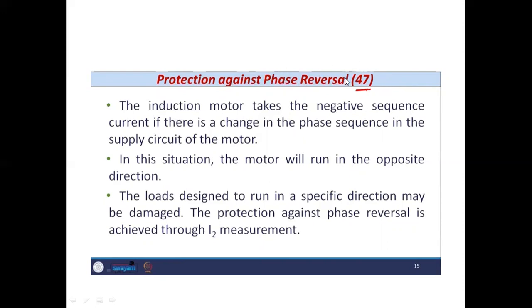So the induction motor negative sequence current, if there is a change in the phase sequence in the supply circuit of the motor, in this situation the motor will run in the opposite direction. The load you have connected with the motor is designed to run in a specific direction only.